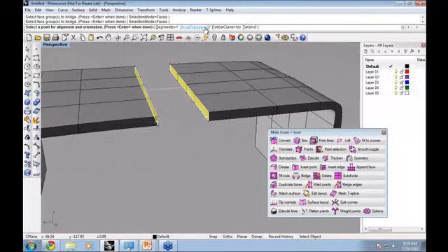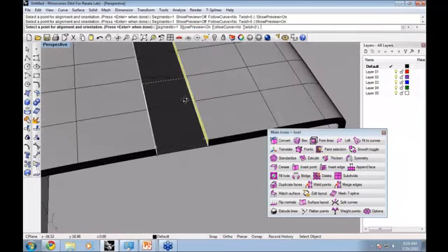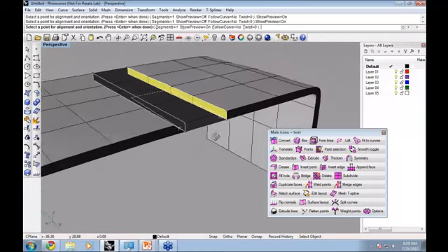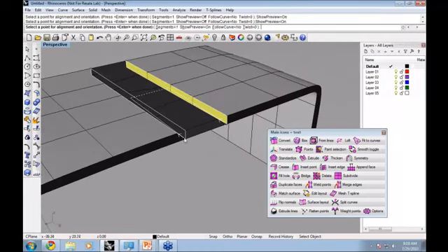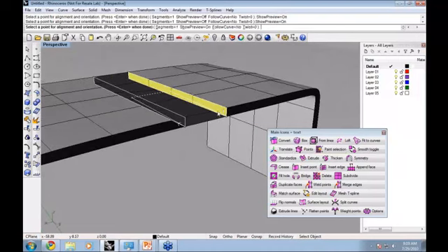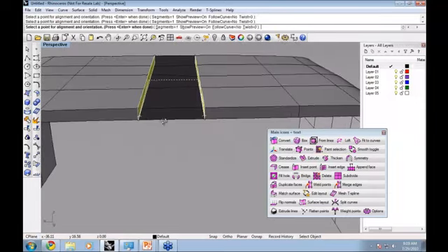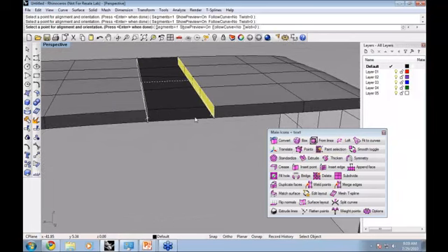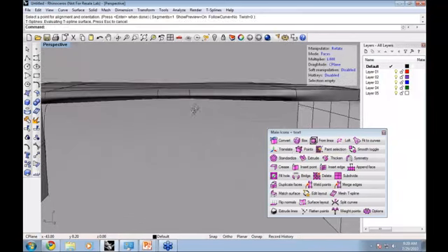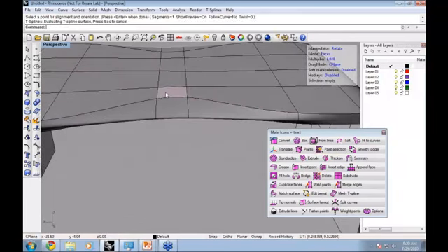And then I can show, there's all sorts of options about what the preview is, how the bridge can be aligned. You can see that these arrows need to be lined up and in the same spot. So if I clicked it and have the arrows moved, you can see the bridge is kind of all twisty-like. So you want to make sure that the arrows are in the same point, in the same location, so that it lines up correctly. But then when I hit enter, you can see that it bridges it up nicely.